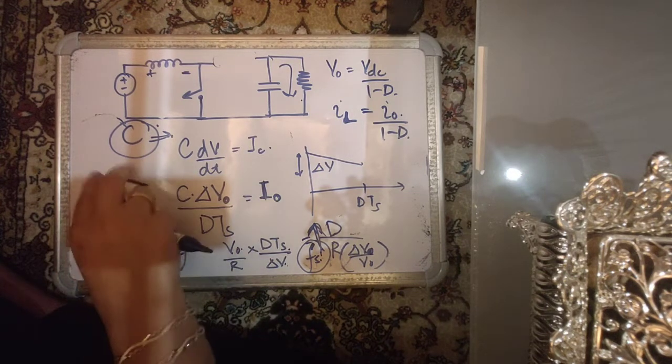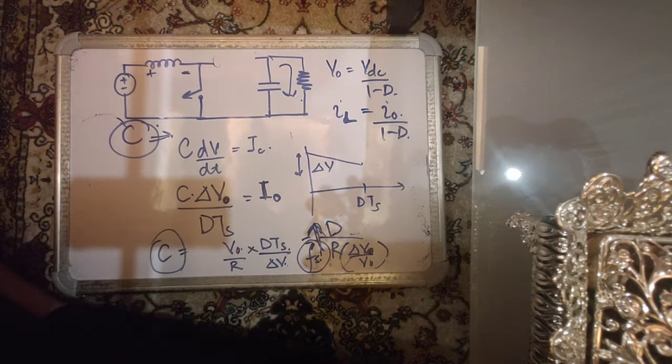So this was about the boost converter, the design of L and C in detail, and some waveforms for continuous conduction mode. We talked about the current second balance, the voltage second balance, and how both L and C ensure that they store and release energy in complementary intervals, but they end up not consuming any excess of energy or delivering any excess of energy.